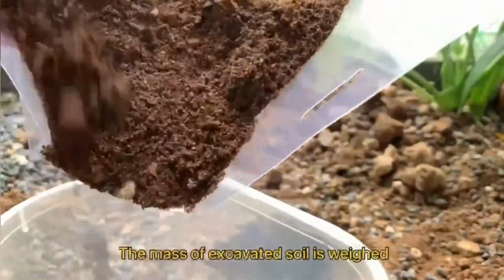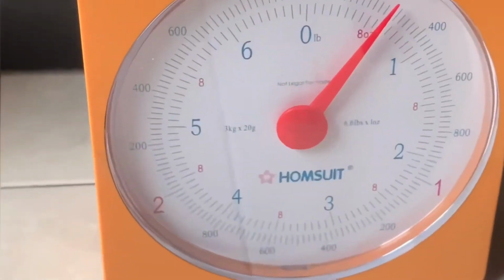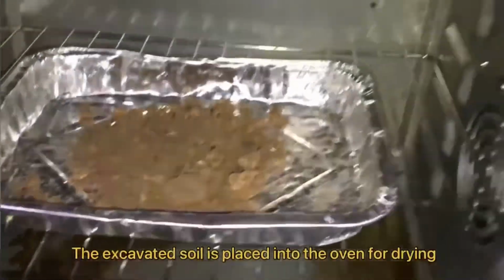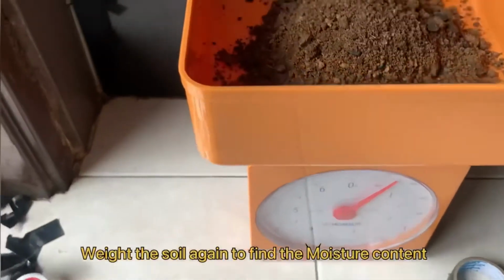The mass of excavated soil is weighed and known as W excavated soil. The excavated soil is placed into the oven for drying. After the oven drying is done, weigh the soil again to find the moisture content.